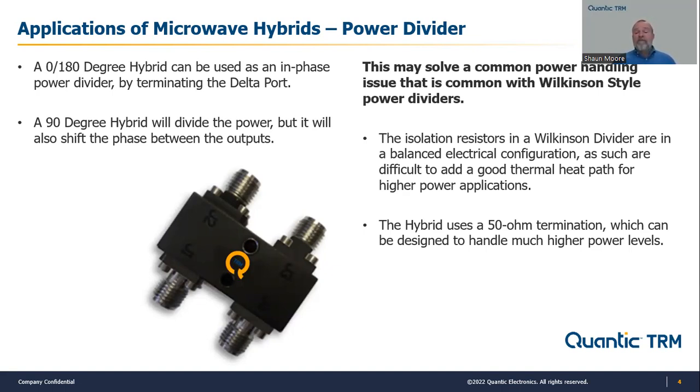Basically, from a functionality standpoint, you're going to operate very similar to how you would with the Wilkinson-style power divider. Both outputs will be in phase with each other, and from a functionality standpoint, will behave very similarly.